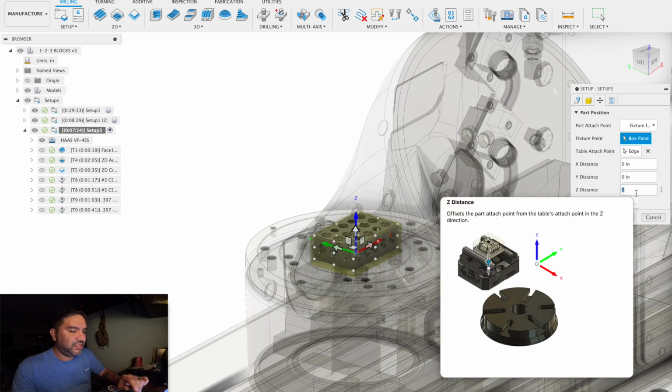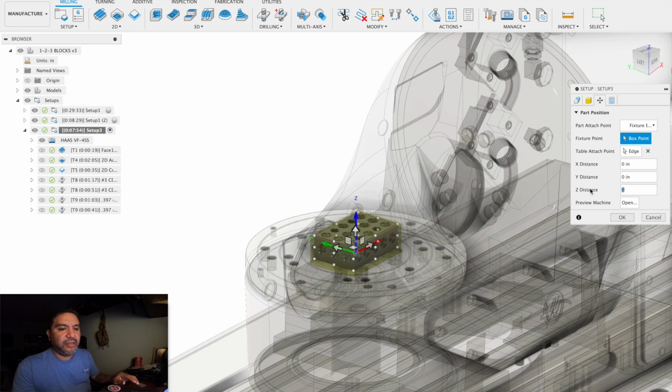If you're using Haas TCPC, you have to set that number first, then you can use your Z-axis probe, and those two numbers will work together, and you won't have to do all of this stuff every time you do a program. But this is how you set it up. You find that swing, load it in your macros or load it into your program here.